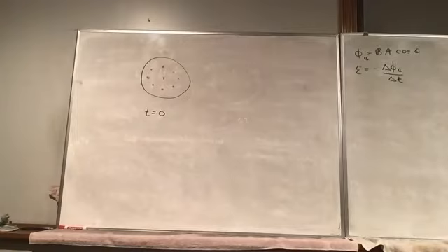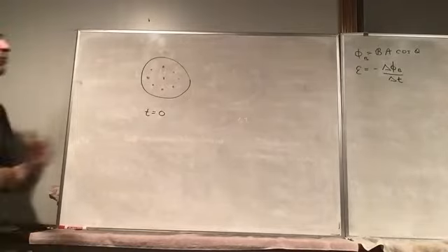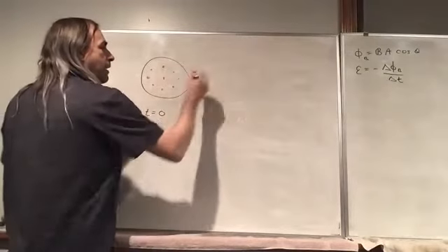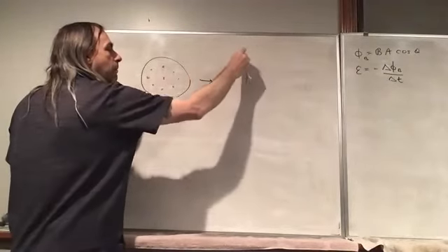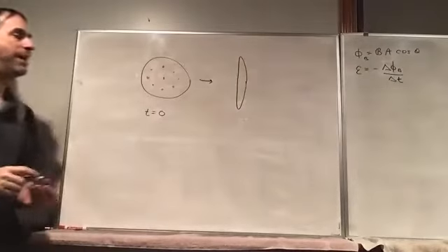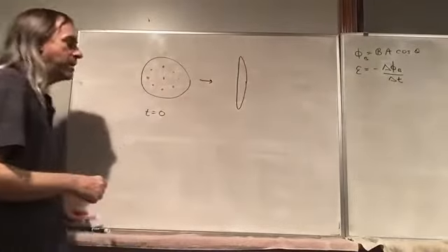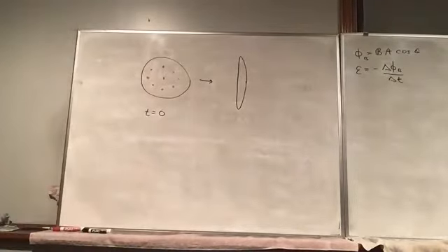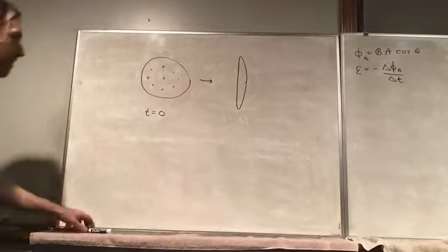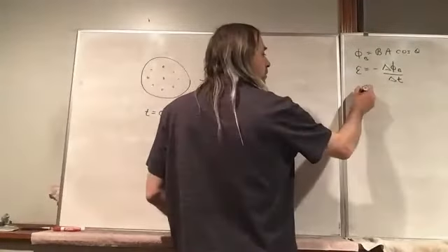Okay. But another way you can do it, let's say you have an actual coil here. Say you just push on it and you turn it into this. So it's the same length of wire. It's the same magnetic field, but the flux would change in this case. So you would have an induced current in that case as well. So yeah, anything that changes a flux will produce an induced current. And a generator is a very important example of that, where the EMF would be described by a sine function.